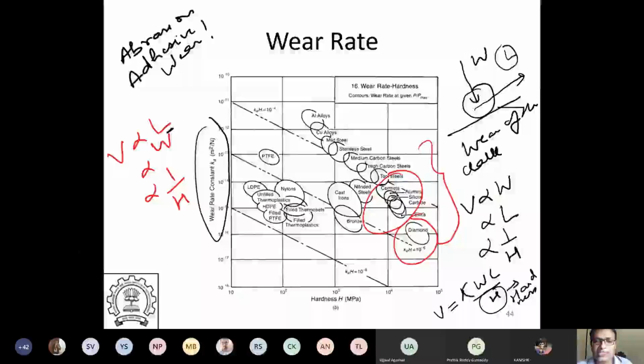So you would see that most things where you want to make a stylus for hardness measurement, all the profilometers, are made of diamond. All the key things where you don't want wear would be made of diamond. Very hard tools are made of diamond, and the usual suspects are diamonds and ceramics, which have very, very high hardness. Of course, high carbon steels and tool steels are reasonably high, but these are the things which have higher wear resistance. Okay.